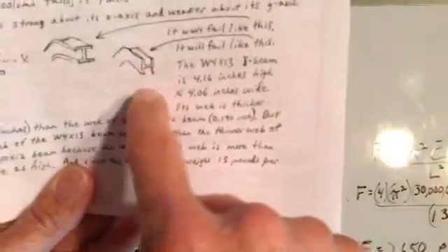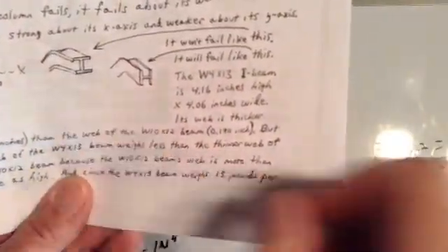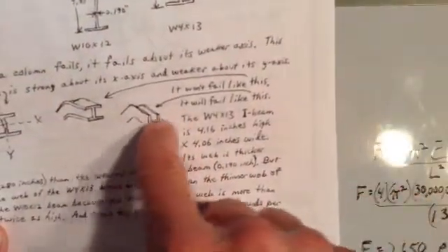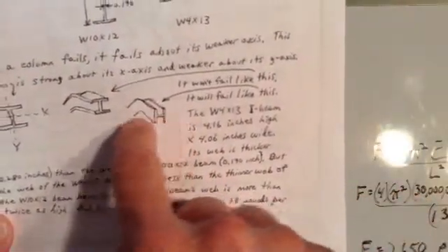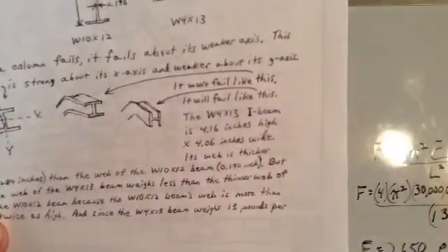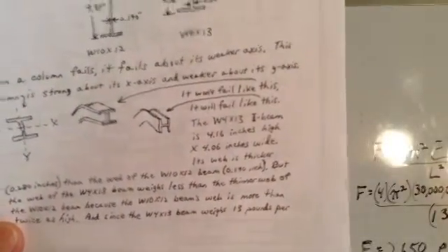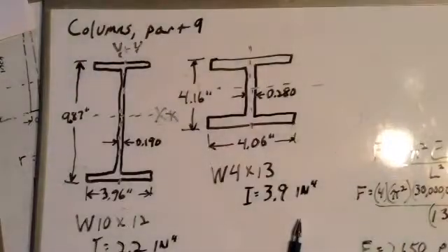It'd be like looking at it with its eye shape. The middle of it goes off to the right here in this picture. And if it's looking like an H, the middle of it will go up or down, because the axis here is the weaker axis. It's the axis with the lower moment of inertia and the lower radius of gyration.